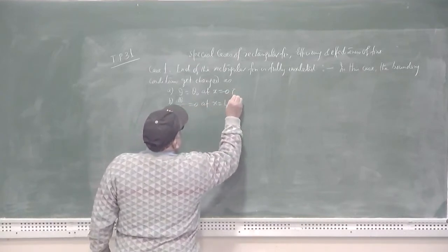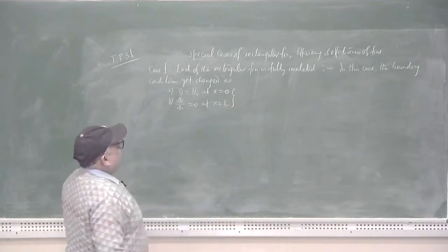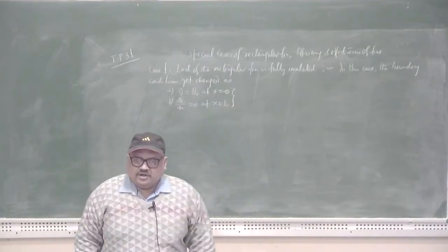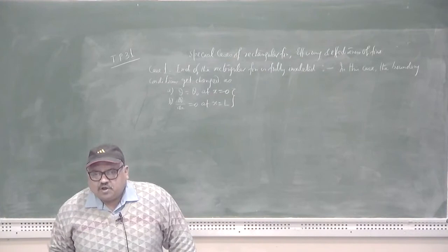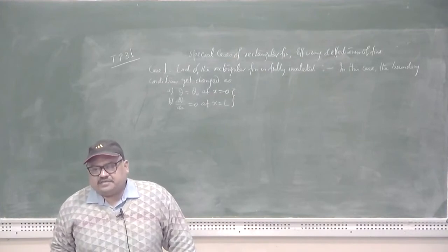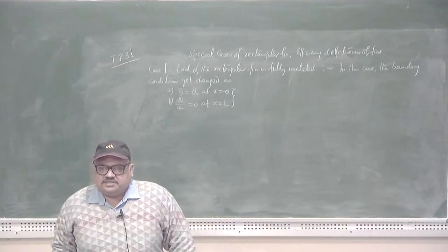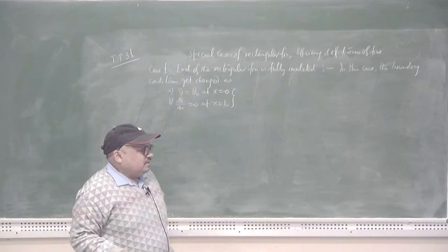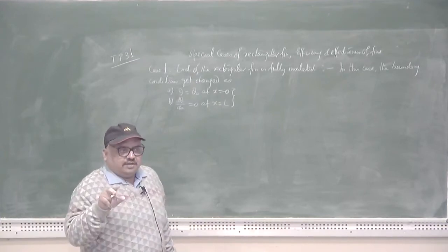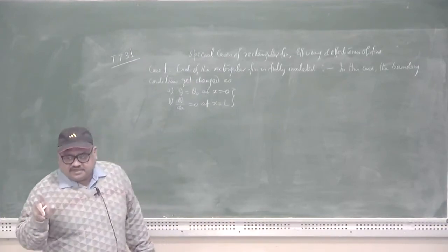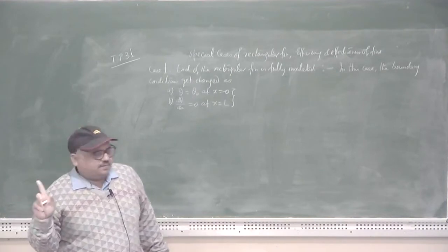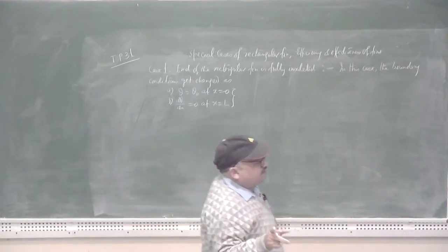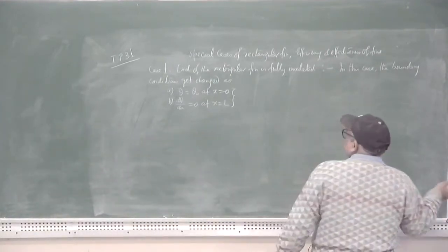So, these are the two boundary conditions by virtue of which we come to know how the constants of integration, as they appear in equation number 2, the generalized solution, theta is equal to C1 cosh mx plus C2 sinh mx, where C1 is equal to A plus B and C2 is equal to A minus B, change.